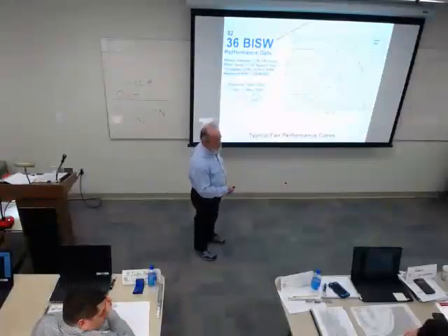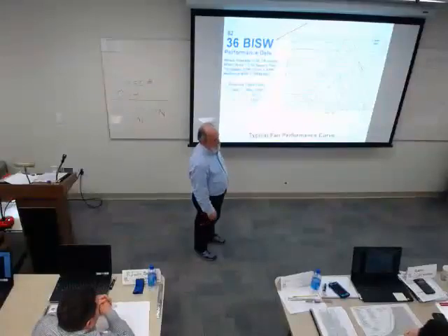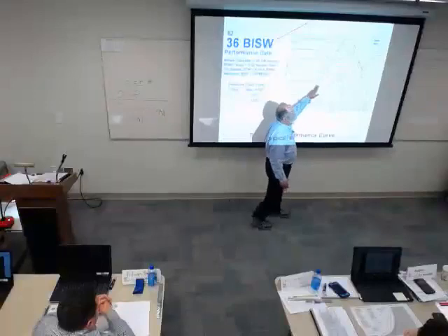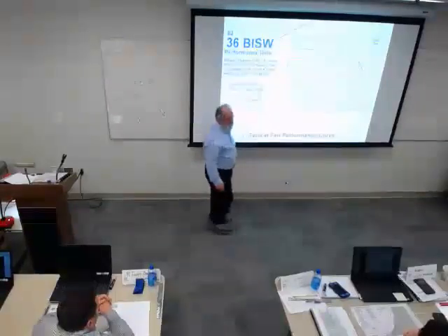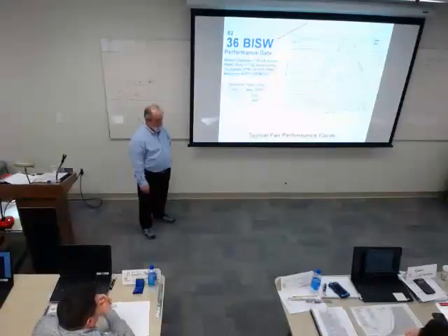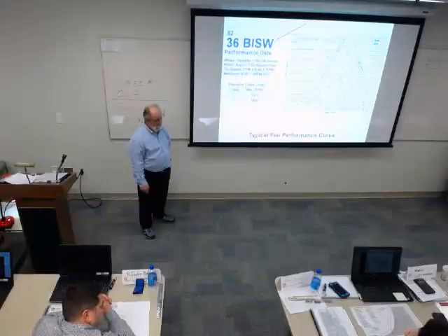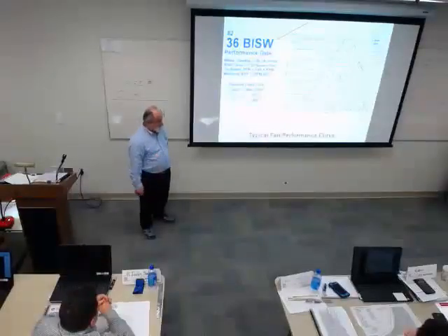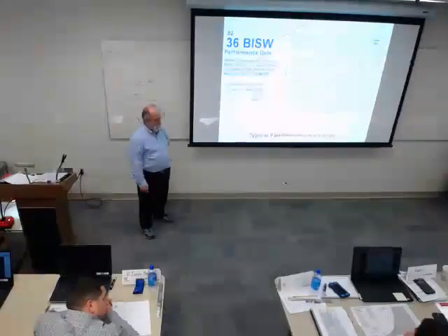So the fan would be too small for the motor? No, the fan is poorly selected. It was selected too close to this line here. We have an old theater that has this massive fan, and they ran into that problem and blamed it on a bearing issue. Bearings could change things, but what we found the solution was to slow the fan down.